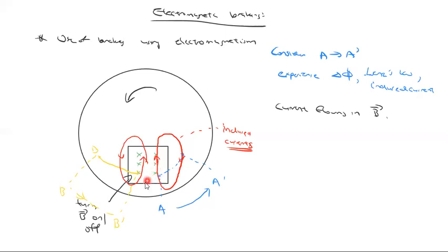And because you now have current flowing in the magnetic field, by the motor effect, it experiences a force. You can think of the right-hand palm rule: your magnetic field is going in, your current's going up. This force will be to the left. So this will generate a force, which I will probably have to use a different color for. Let's do that and draw that. So that will generate a force left.